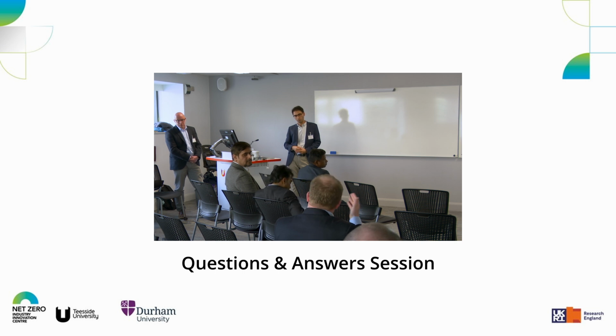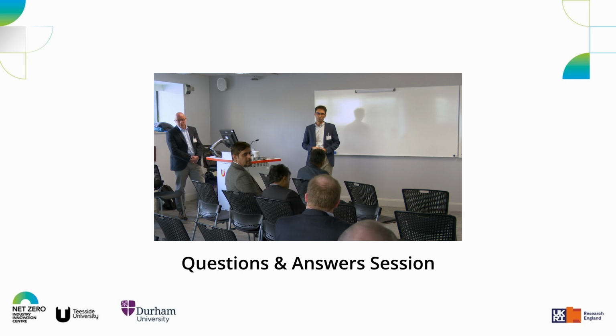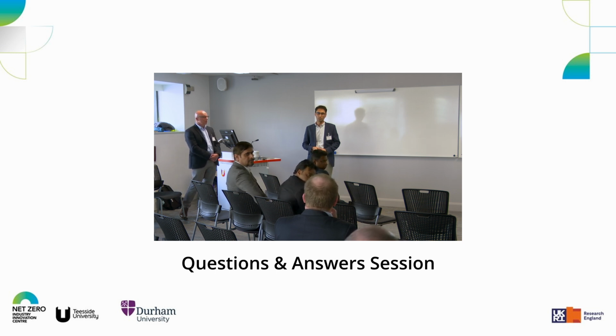When you model a pre-existing defect in hydrogen, that's when you can get lower fatigue lives. If you have good inspection technology which gives the pipeline a clean bill of health, then you don't have to consider that. But doing the fracture mechanics on that is where we do a lot of our work.